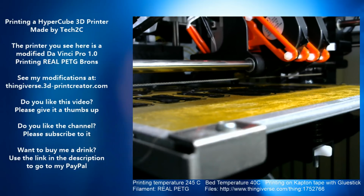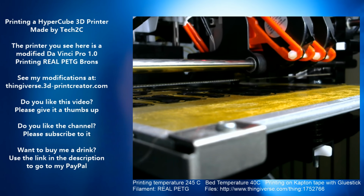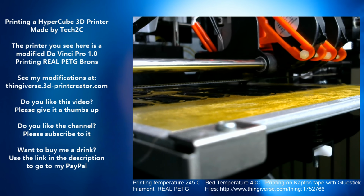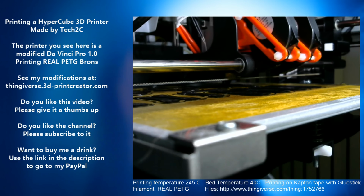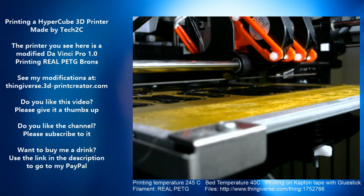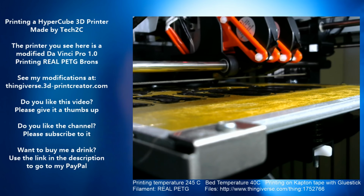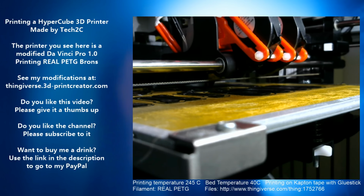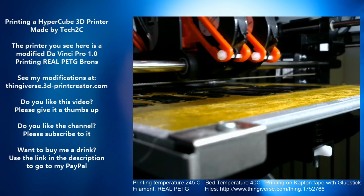And in the meantime, my printer is busy in the background making the parts that I need for my Hypercube printer. I'm printing in PETG, which is pretty difficult on this printer because it's a Bowden extruder printer. 245 degrees Celsius with a 40 degree printing bed.